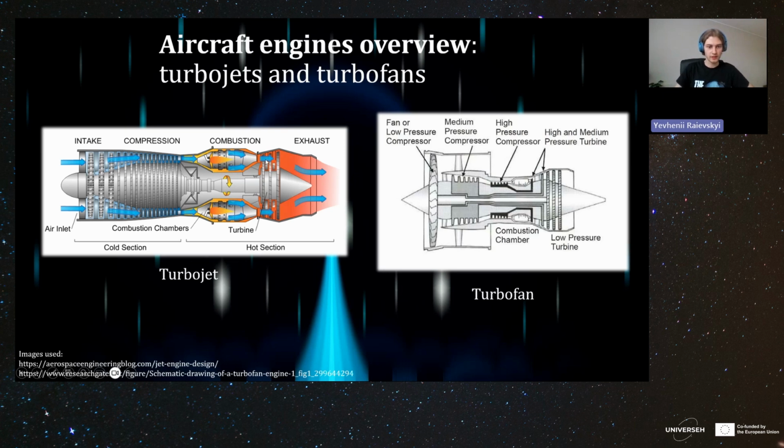So if those turbine blades are driven because of the influence of this exhaust gas, basically this gas does some work on the turbine blades, and this energy is transferred through the shaft, causing the compressor blades also to rotate. And if they are rotating, they accelerate the air molecules, causing them to move forward, and the cycle is completed.